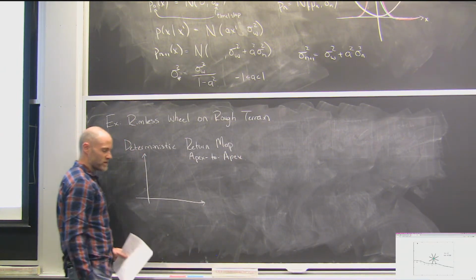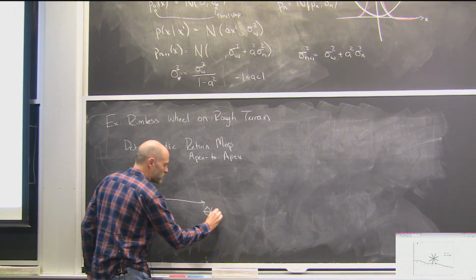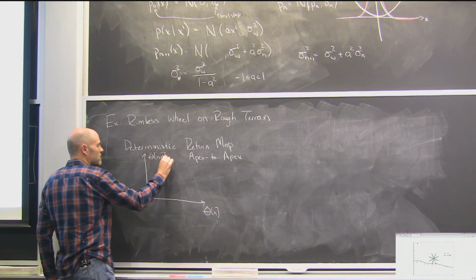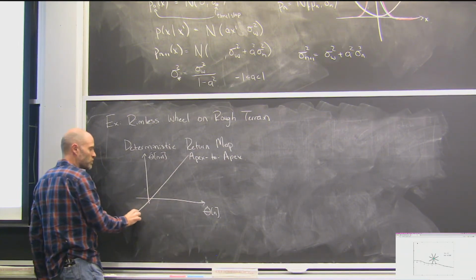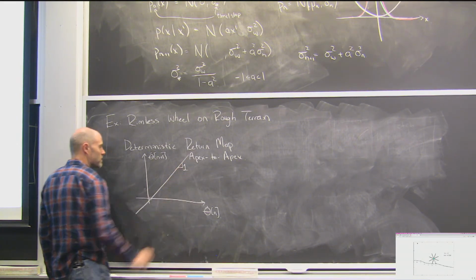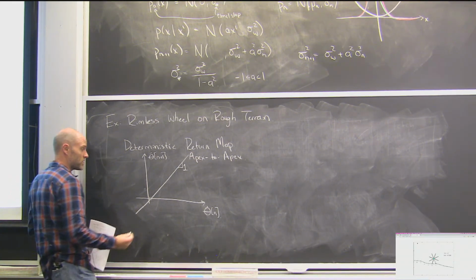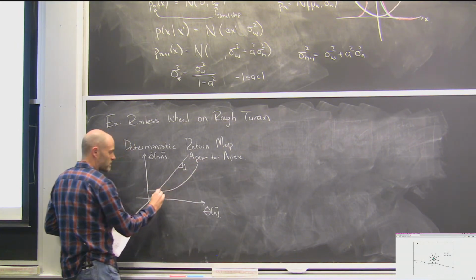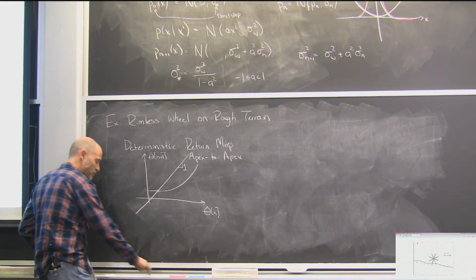So at the apex, theta is fixed. The variable of interest is theta dot. The velocity of the leg at the apex, the velocity of the leg at the next apex. For these discrete systems, I'm going to draw the line of slope 1 that tries to go through the origin. And we know that the original system had a stable rolling fixed point, and indeed the deterministic return map looks something like this, with a stable rolling fixed point here.